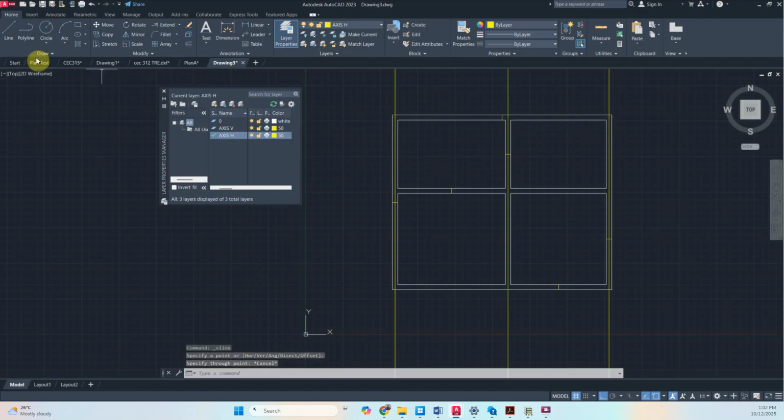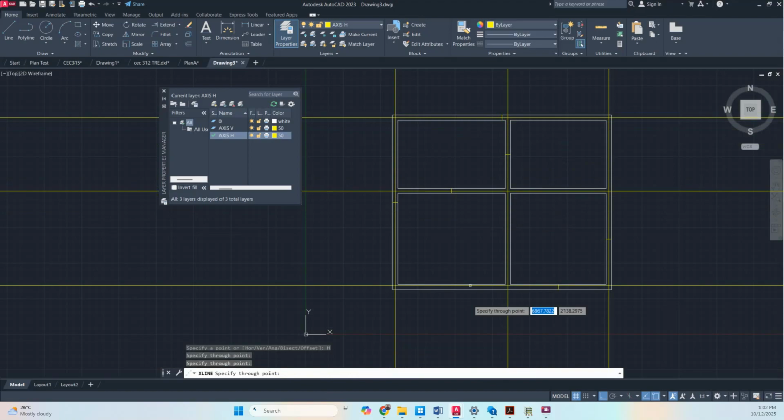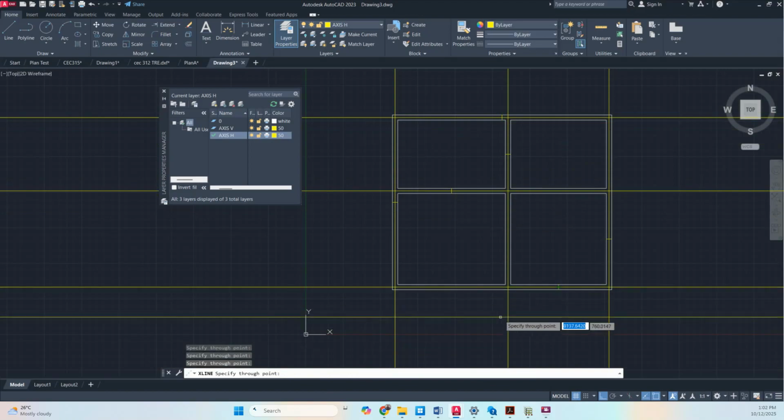To make it easier, just click on it, then you tell it you want horizontal, H. Enter, so it will give you horizontal directly without stressing yourself. So you can just click on it at the center. So I'm done. Now that is all on that.